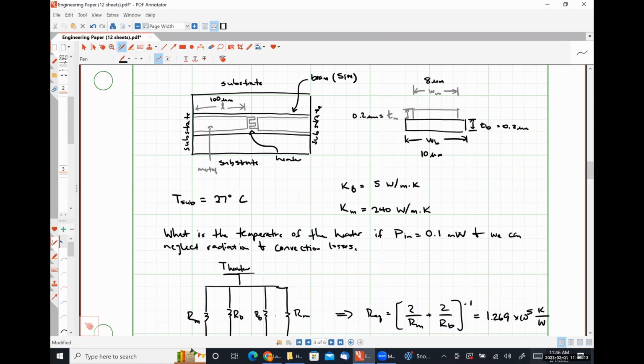So this particular structure is what's called a thermal bimorph because it's made of two different materials, and those two different materials are going to have different coefficients of thermal expansion. So effectively, we have two materials that are pressing against each other, and if we assume that the substrate isn't going to deform, when we heat that structure, the whole cantilever is either going to wind up deflecting up or deflecting down to take into account that thermal expansion.